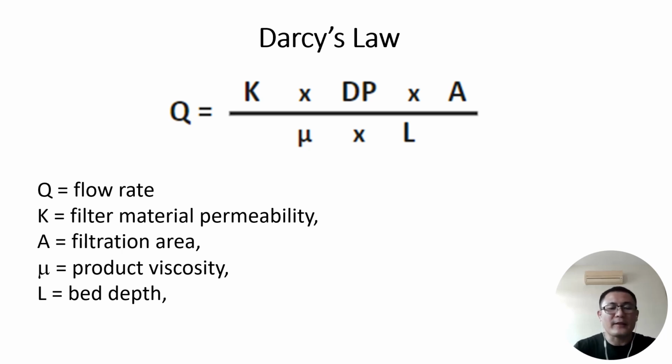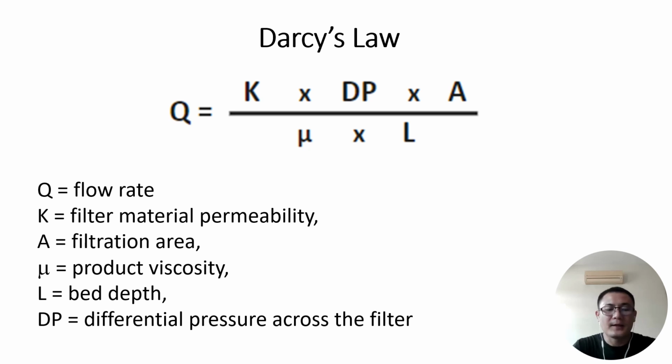Darcy's law is fundamental in understanding and optimizing the filtration process. In our case, the filtration process refers to sterile filtration. Darcy's law describes the flow of a fluid through a porous medium. In our case, the porous medium refers to the sterile filter. So, let's review this Darcy's law again.